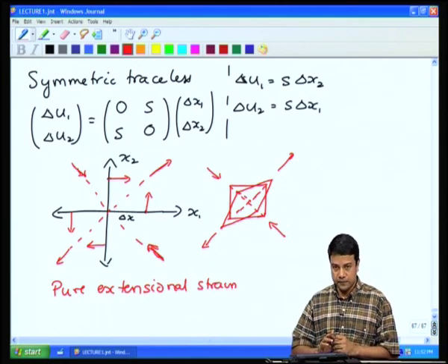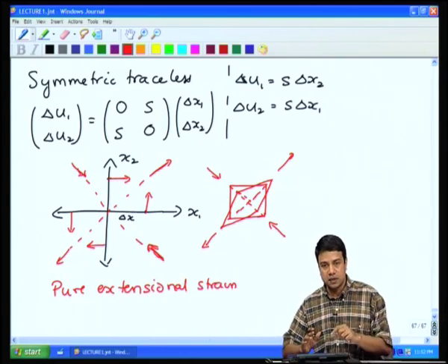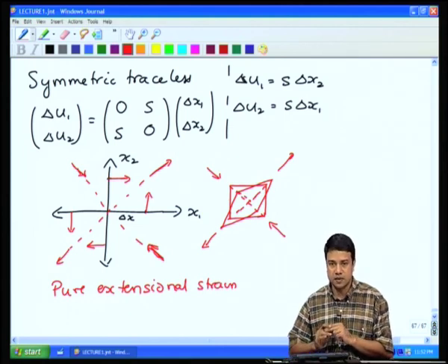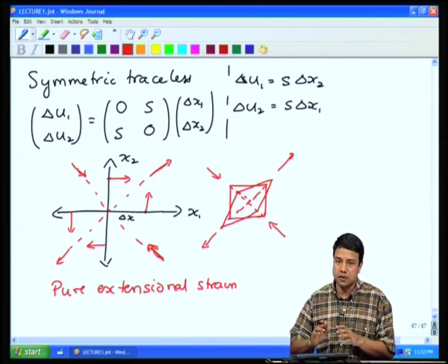In a fluid, we will see a little later that a solid body rotation cannot generate internal stresses, because when you take an object and rotate it, if it is a solid body rotation, the distance between nearby points has not changed at all. There is no extension or compression of distance between nearby points. So, the stresses that are generated cannot be due to the solid body rotation.